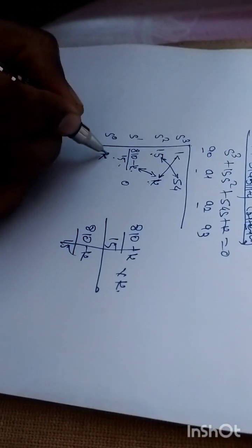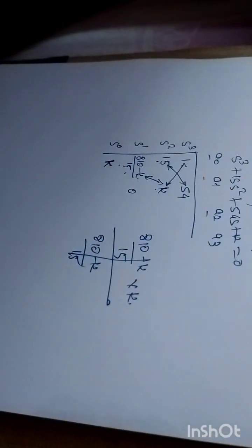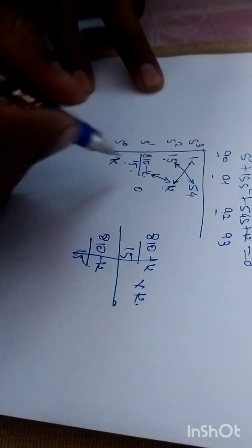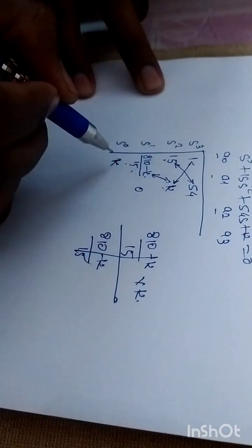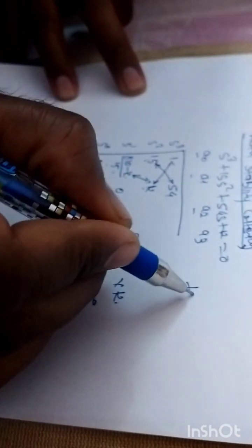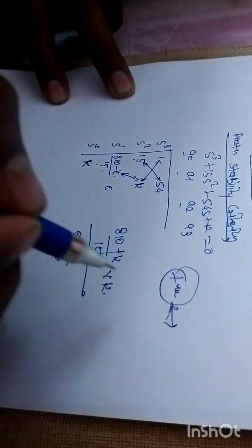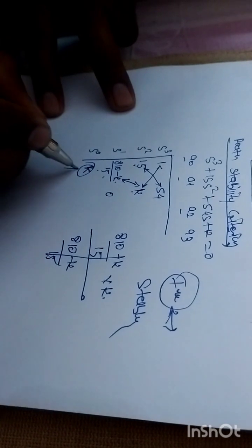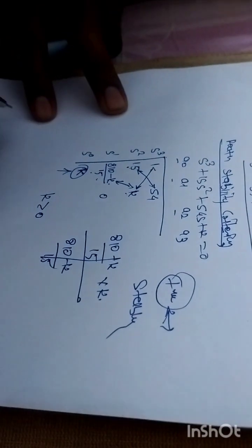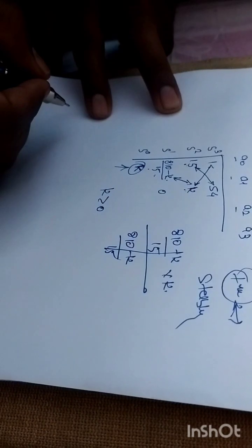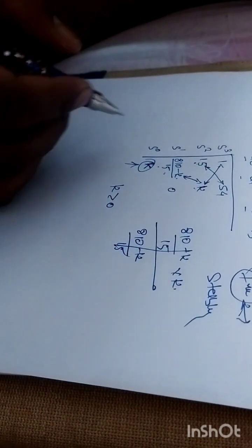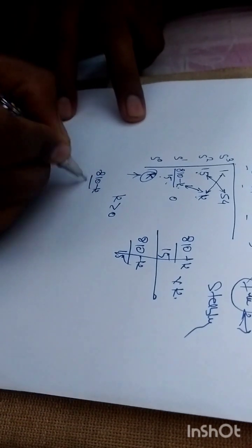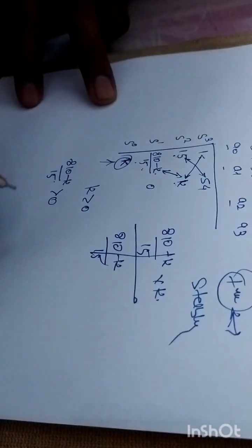K. Now from the stability point of view, as far as this Routh stability criteria is concerned, all the elements present in the first column should be positive. Then and only then can we say that this system is a stable system. So when we consider this last element, it has to be greater than 0. Now the other element in which we have this constant value is 810 minus k divided by 15. Again it should be greater than 0.